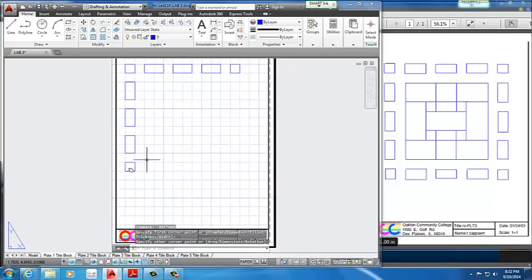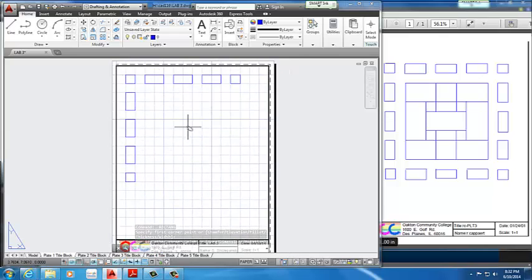I prefer keeping it clean, not drawing too many lines to divide this up. Now let's say I just want to copy these. I feel like using the mirror command, I don't mind doing it, but I don't know where the snap center option is. I don't want to work around that. For some reason, I just want to make a copy.